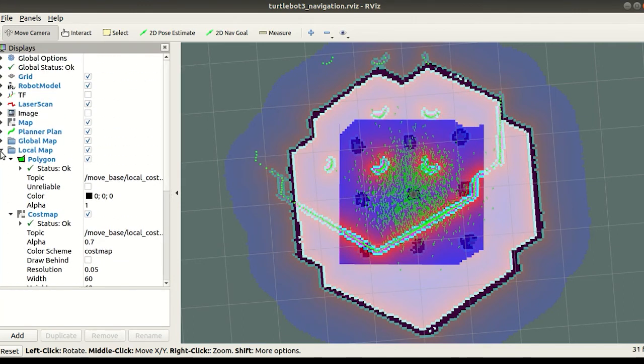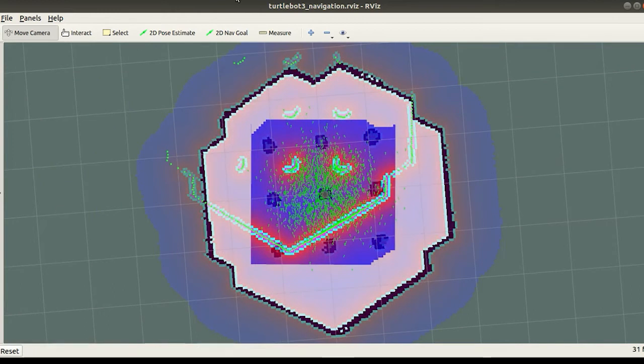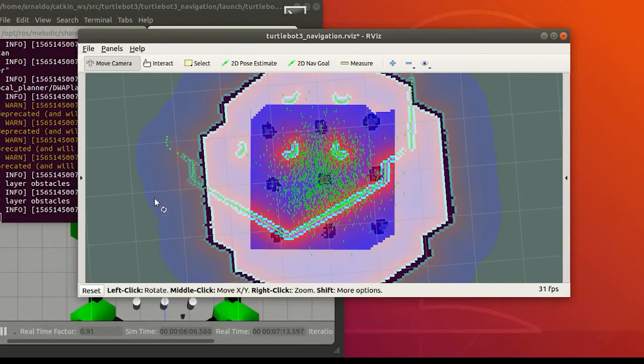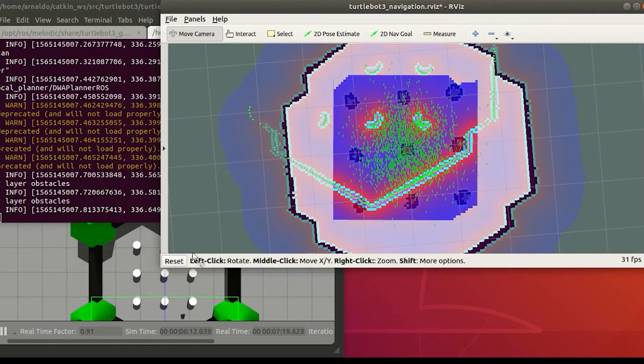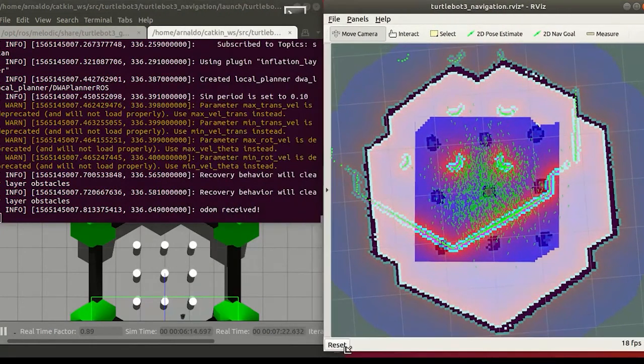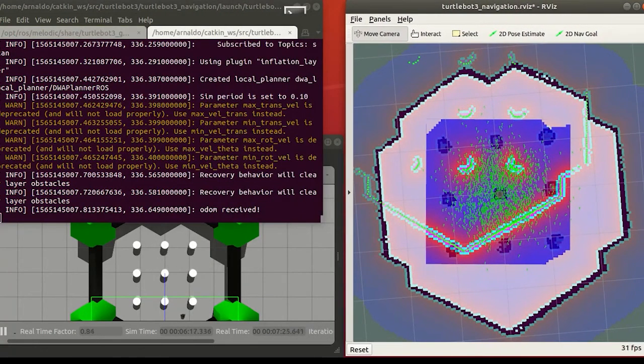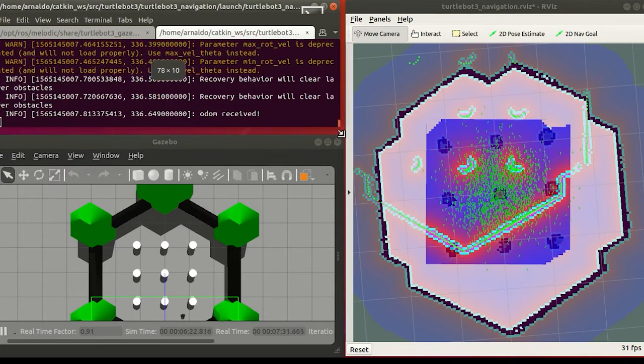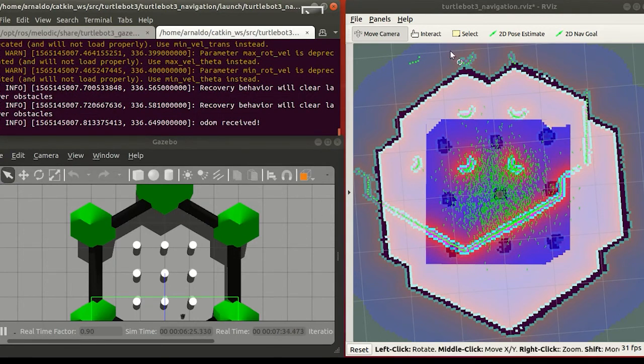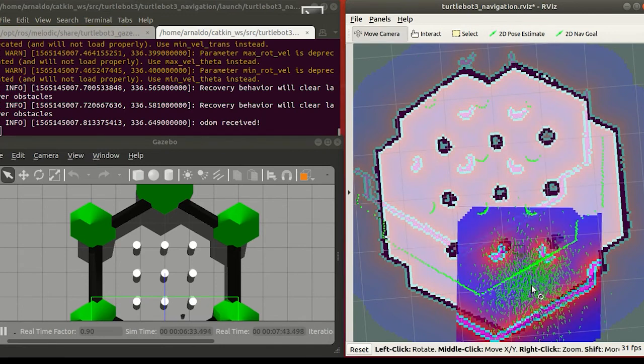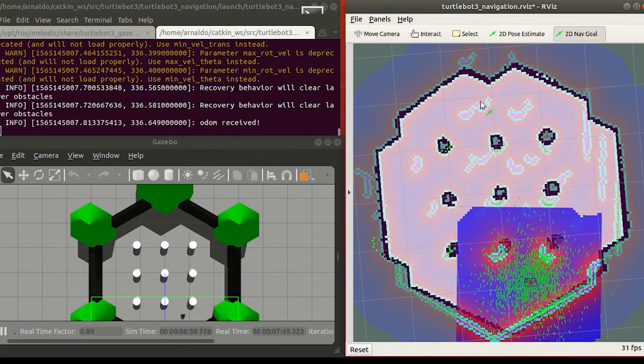You can see green particles except the laser data. Those are just guesses for the position and direction of the robot. Those are just random guesses, and the wrong guesses will be discarded as the robot moves around. So just reshaping it according to desire, we are going to give an estimated pose of the robot with its direction. Now you can see it is roughly aligned.